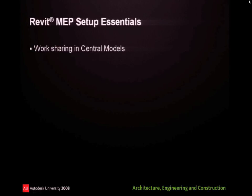I didn't really talk about central models yet. Our company is pretty much standardized on central models. We typically do large projects where we have to have multiple people inside the model. So we're going to want to set up a central model by invoking the work sets. So what does that mean? Why am I mentioning that? Well, you're going to want to logically break that project up. And let me show you how we've done that.